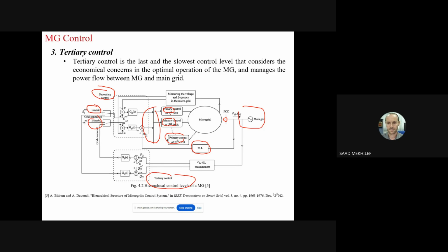So you need to have the energy management within this, because, for example, you have power that comes from the PV. That PV power goes to the load or goes to the battery. Okay, for example, you have less power. Suddenly, a certain load turns on. So where does power come from? Does it come from the battery or from the diesel generator? You have to turn on the diesel generator. So when the state of charge of the battery goes low, do we have to turn on the diesel generator or what? So this is what I call the energy management within these resources.